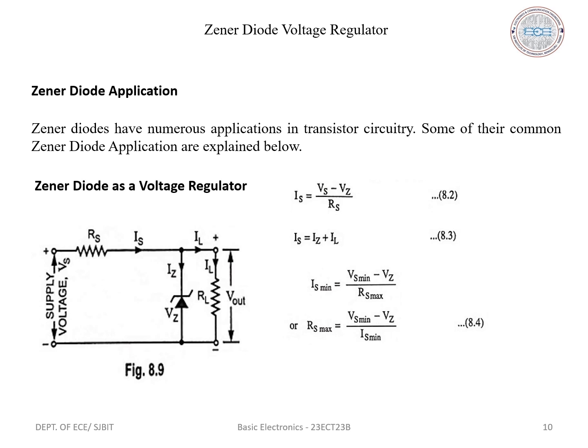The maximum current in the circuit is given by Iz maximum equals Pz by Vz, where Pz is the power rating of the Zener and Vz is the Zener breakdown voltage. When the input voltage Vi is less than the Zener breakdown voltage Vz, the diode does not conduct and the output follows the input. However, when the input voltage exceeds Vz, breakdown occurs and the voltage across the output remains constant at Vz.